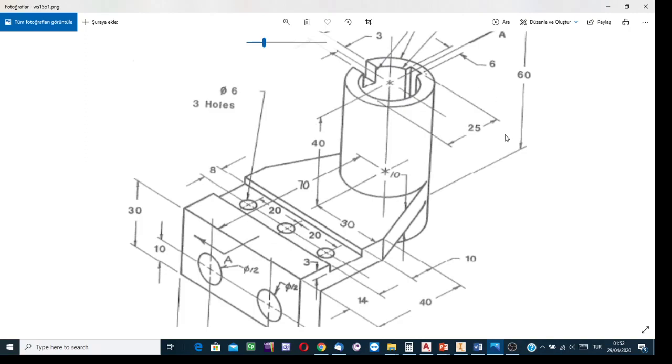Well, and then here there is a dimensional constraint. From the reversal of direction point of this circle, it is this point, to the profile surface of the channel, the distance is 25. Okay. I know that when I try to input this constraint, when I indicate the circle, then Inventor will distinguish it as the center.